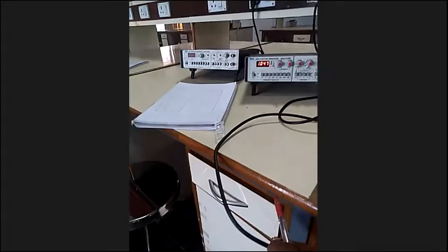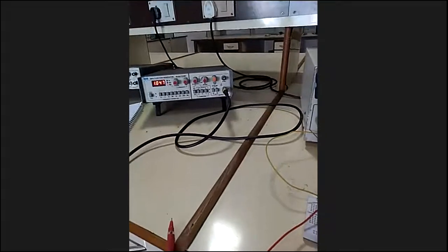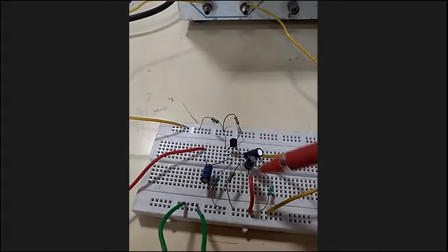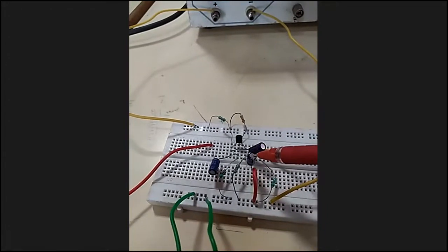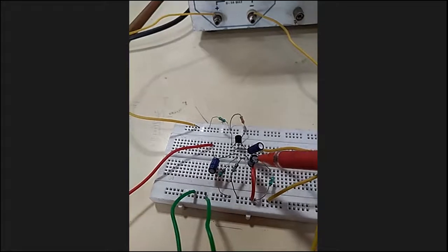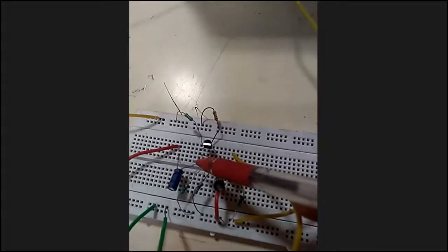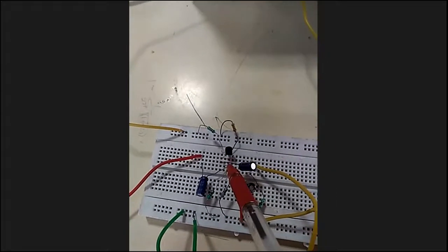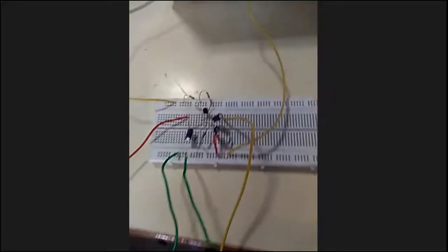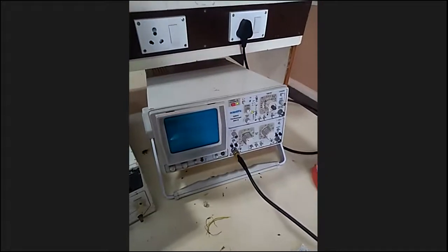You see, this is the input that comes from the function generator. This is the probe, and you see there is a base resistance going to the ground. There is an emitter resistance here, 330 ohms, and there is an emitter capacitance also, right? At the collector, you take a capacitor to the output. The output is a yellow wire, you can see it goes to the CRO. In the CRO, there's the reading, right? So that's how the setup is.